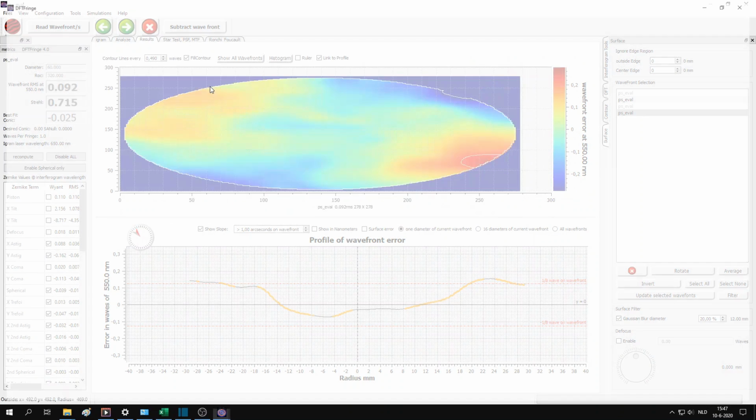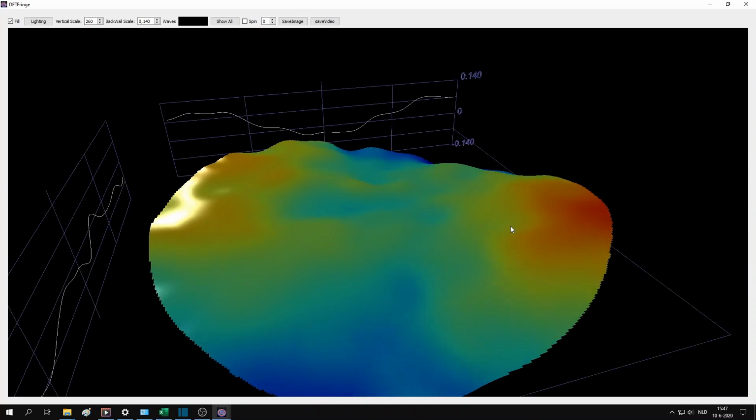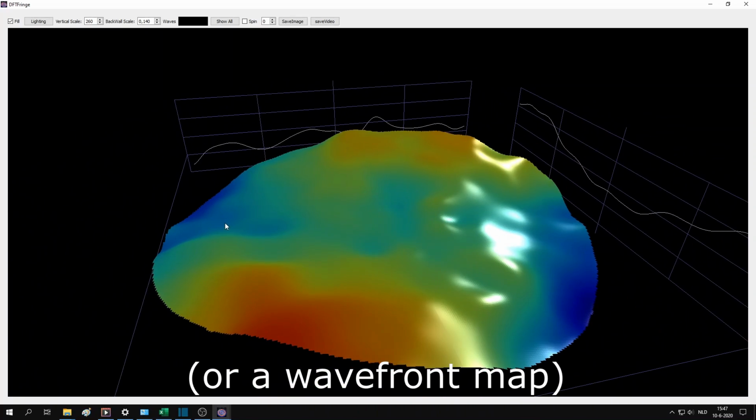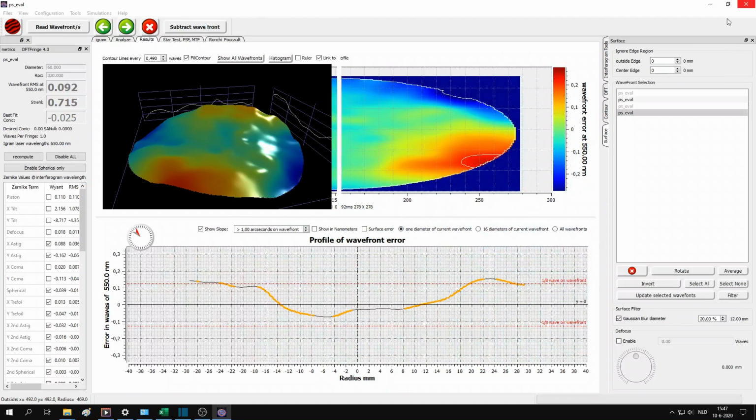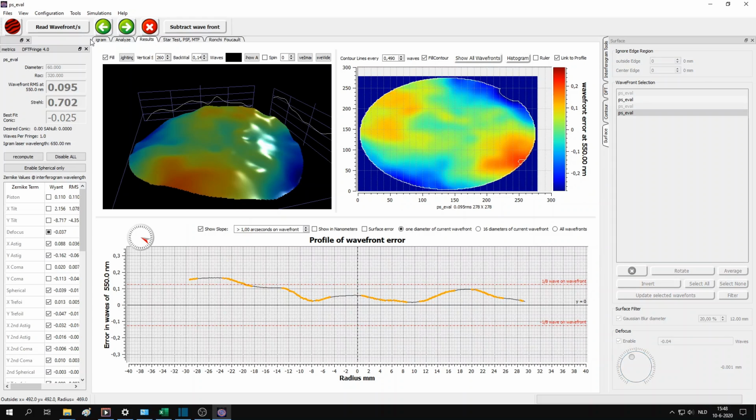It uses Fourier transforms to convert the fringe patterns directly into a height map, and maybe the most amazing thing is that it's completely free, and that's quite remarkable given that commercial interferometer software is quickly a few €1,000 or more. Among a ton of other things, DFT Fringe can also calculate the best conic fit for the surface, which we will use as a parameter here.